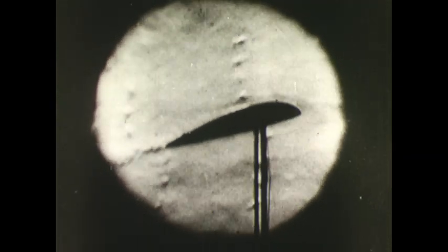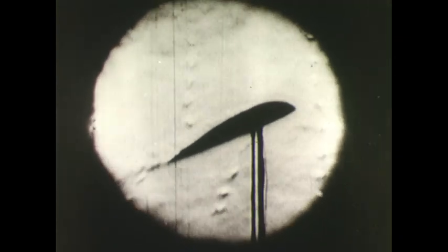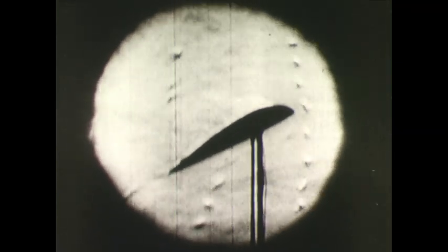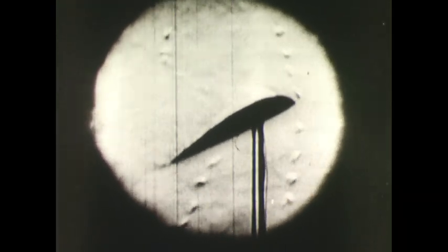The apparent speed is further reduced by slow motion. The angle of attack is being increased above the stall. Turbulent air at the trailing edge starts flowing forward up the back of the airfoil, and the smooth or laminar airflow leaves the top surface. Air is obviously flowing into the wake from above and below.